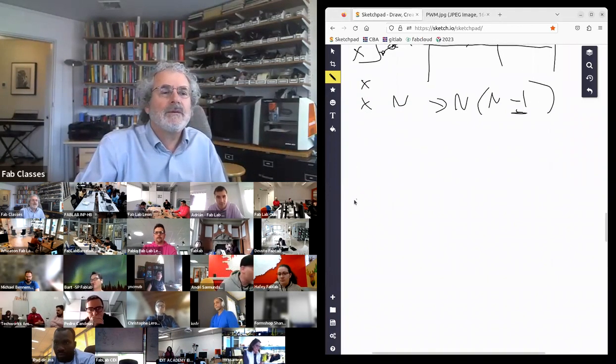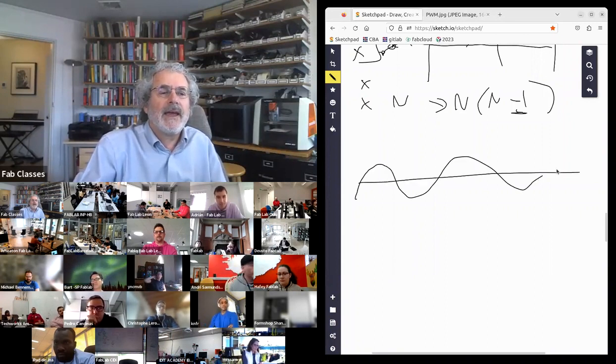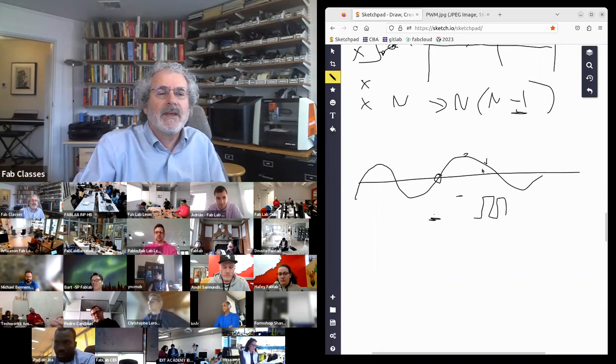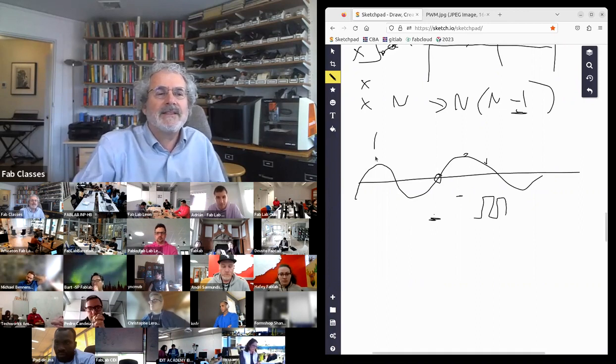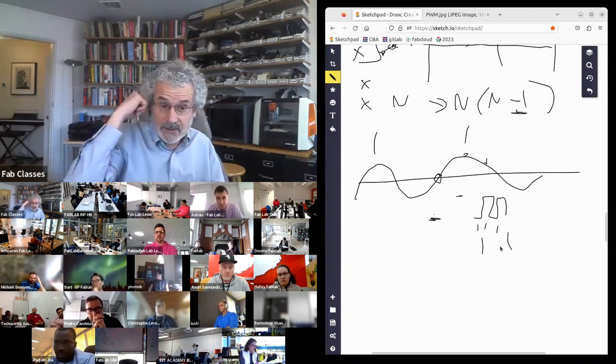audio, my voice has a shape, the waveform. And when we're crossing zero, there's no signal. When it's loudest, the signal is strong. And in between, I'm varying the pulse rate. So to vary the frequency, that's this time. To vary the volume, it's the on time versus the off time. And I've got a high frequency that I'm using to generate the pulses.